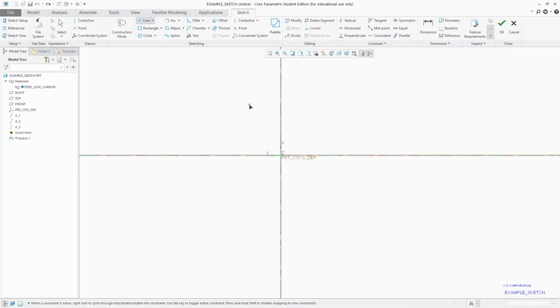So we make our geometry first, and then we define the dimension and the value. Like we have selected line, and you can see here in brackets the L is the shortcut for activating this. If you really want to activate it very fast, then you can just press L and this tool will get activated.